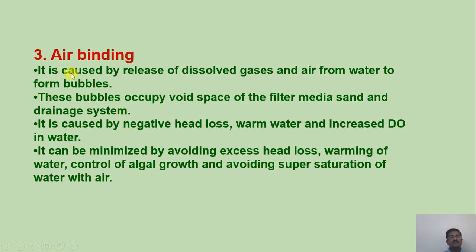Air binding. It is caused by the release of dissolved gases and air from the water, which form bubbles. These bubbles occupy wide space of the filter media, sand and drainage system. It is caused by negative head loss, warm water and increased DO in the water. It can be minimized by avoiding excess head loss, warming of water, control of algal growth and avoiding super saturation of water with air.